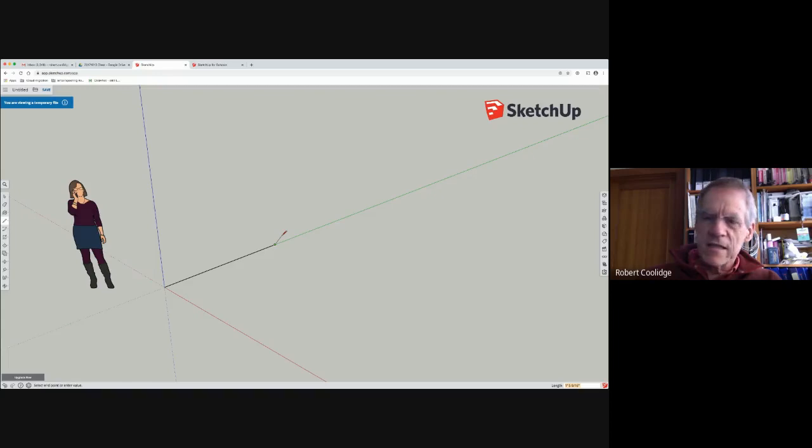You click a second time, and that creates an end to that endpoint. You can see here as I drag off in this direction, it's thinking you want to go in the red direction, don't you? And it's snapping to it, right? You have to get a bit off the axis for it to not do it. There's a way to force it to do these, and they're done with the arrows. So the right arrow, if I just tap the right arrow, now it's really stuck on the red direction. It forces it to be strictly in the red direction.